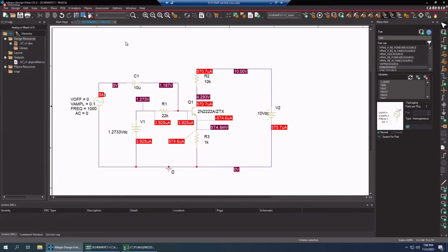I'm wondering if my signal will be a problem for the DC sweep, so let's get rid of that signal source for now, and the cap and all that. That was extra stuff I had you do just to show you the amplifier's performance. Let's get rid of those extra wires too, because sometimes they have problems with extra dangling wires. Okay, so we're good. Now we'll set up a DC sweep in our simulation.